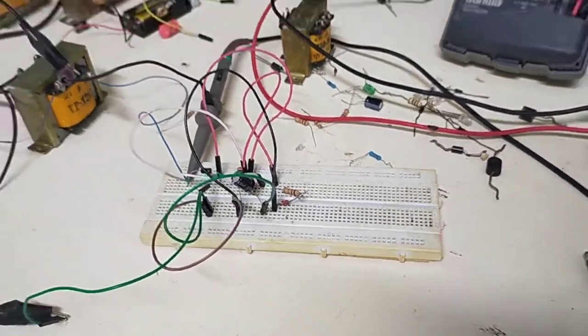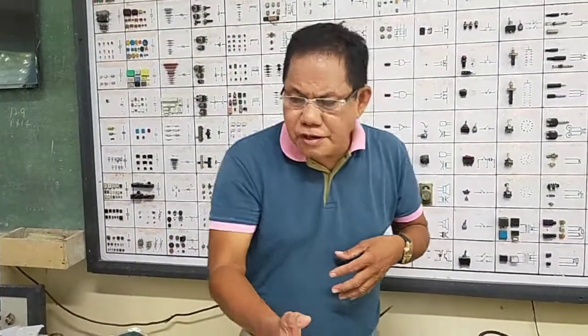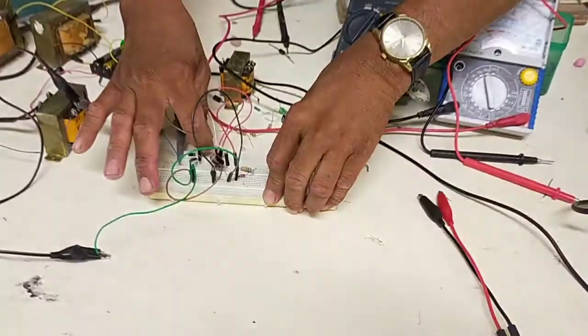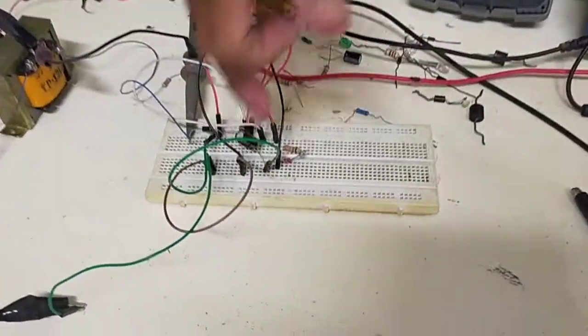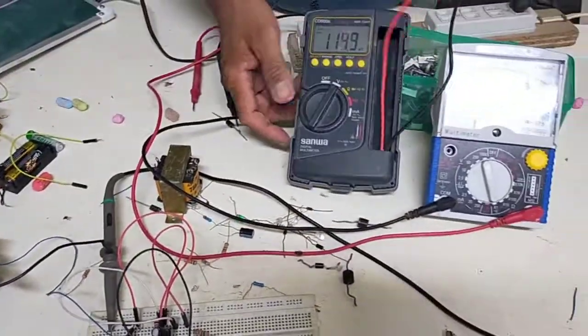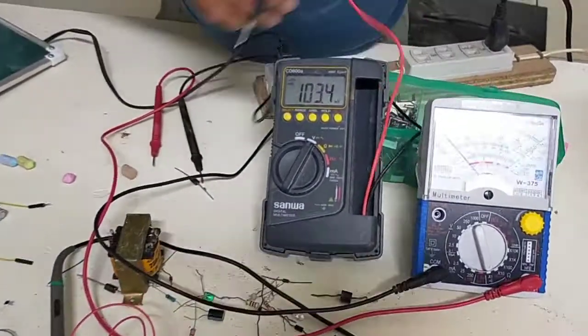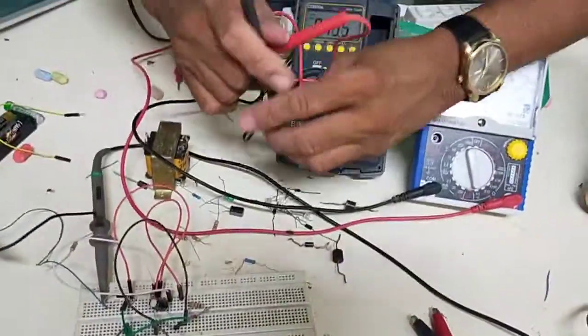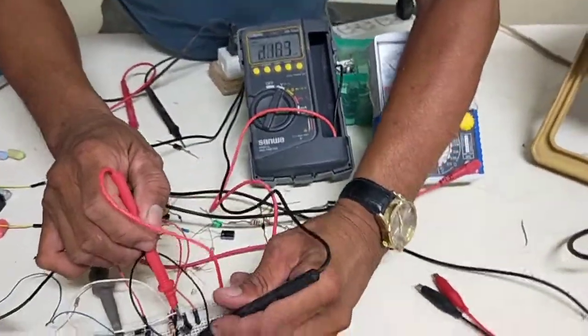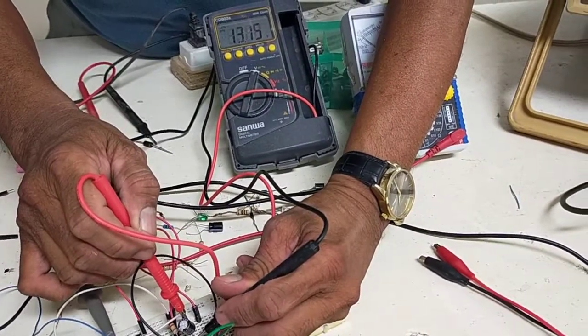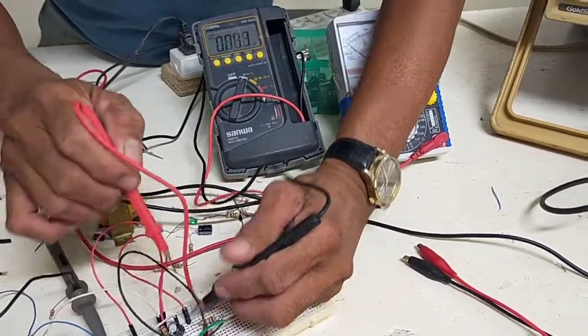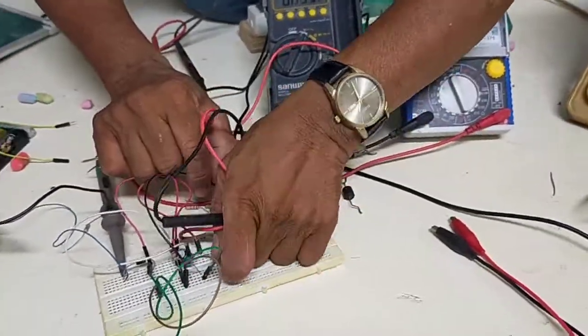When you purchase a Zener diode, you have to tell the Zener voltage. If the Zener voltage of the diode is 12 volts, then the output would be 12 volts, although the input voltage is 16 volts. We will try to measure how much would be the voltage across the capacitor. Again, DC voltmeter. Across the capacitor, the positive is over here and the negative is over here. Let us first disconnect this Zener diode.